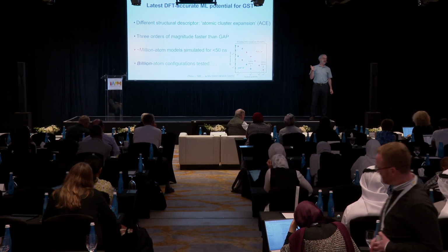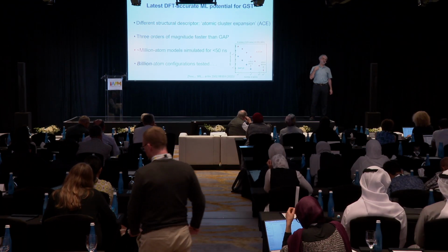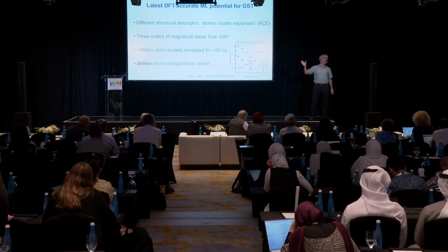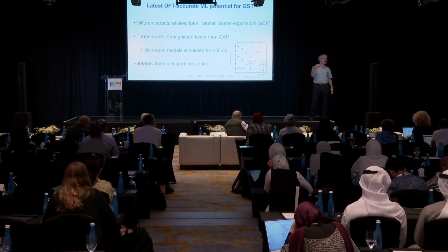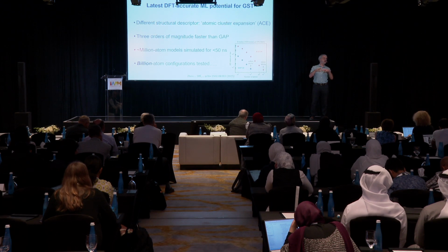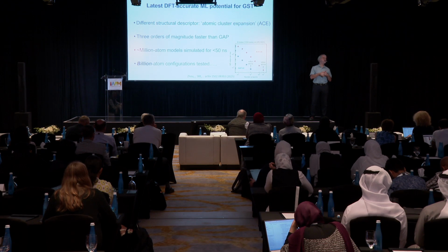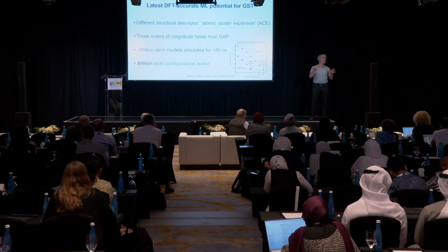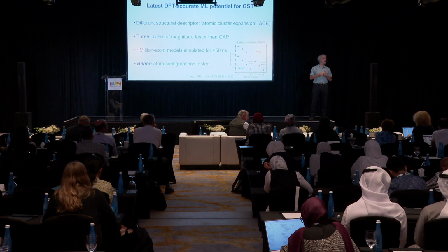We found about 10 years ago that if you can prime the material, you send in a small voltage, which is not enough to switch it, but it actually nucleates the material. Then we showed we can switch it in about 50 picoseconds. So it's a more complicated pulse sequence, but that gets around the intrinsic material limitation.